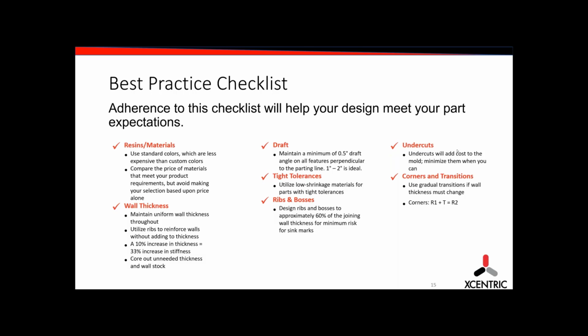If that's the case, yeah, we do that quite a bit. There's a lot of devices that may take a couple different IDs, and if the geometry makes sense, we can do swappable inserts to create multiple designs out of one tool. In doing that, you can introduce witness lines or parting lines, depending on how that insert's created or the design of the part. That would be the only drawback. Okay.